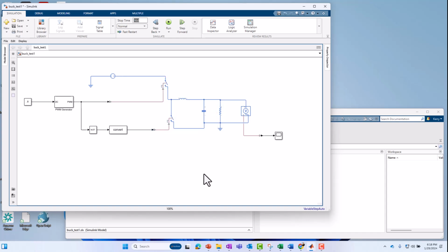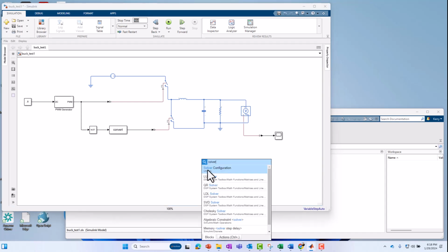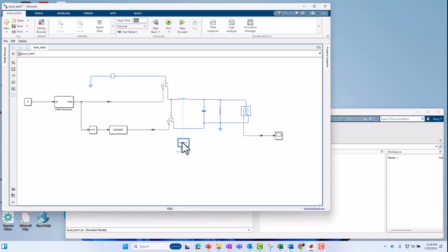Okay, so another thing I need in this model is also basic infrastructure to run the Simscape portion of this model, which is called a solver configuration block. So I'm going to just type solver. And again, you'll find that like utilities, the same place I showed you earlier in the Simscape library family of blocks. And if you like to pretty things up, you can always drag blocks around and rearrange them, slide them over, and so on and so forth.